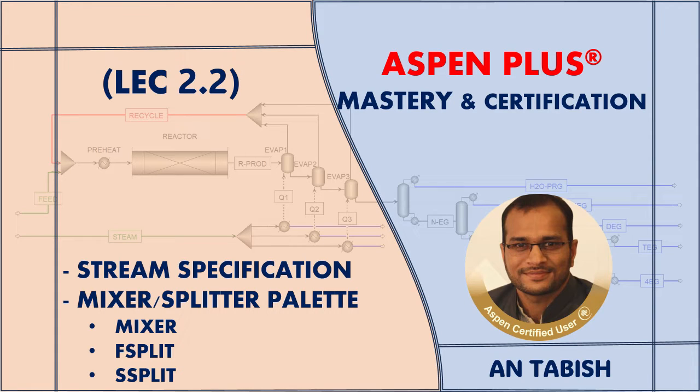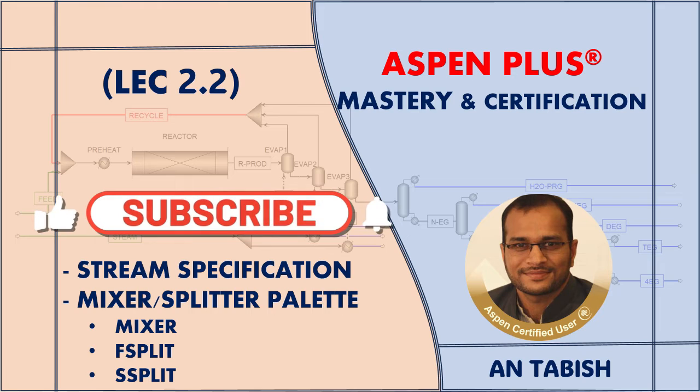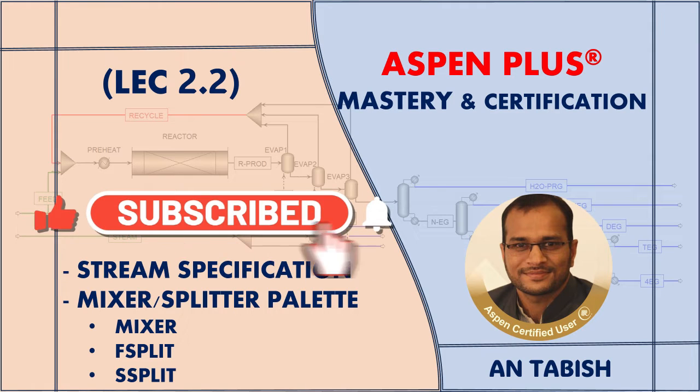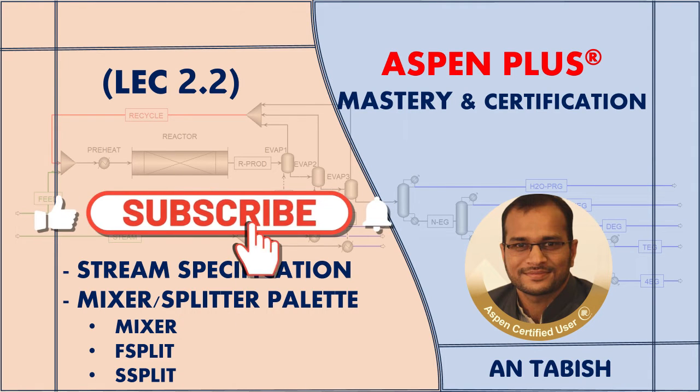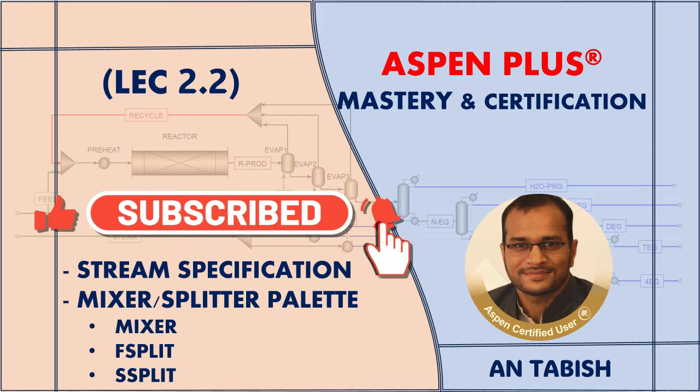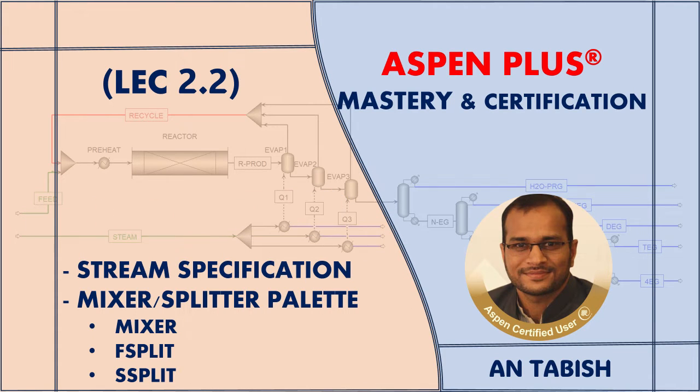My name is Tabish. In this video, we will learn how to define the specification of a process stream. We will consider a process stream that has conventional components as well as solid components, and how to simulate mixer, flow splitter and substream splitter. These three units are available in the mixer splitter palette in the simulation environment of Aspen Plus.